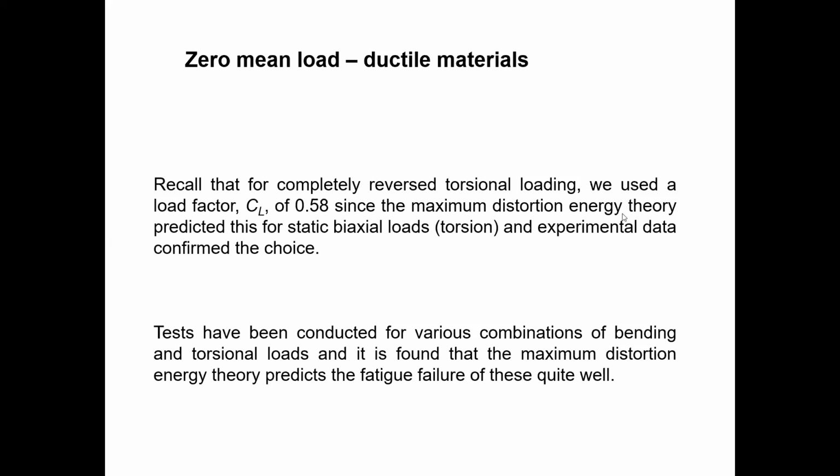Since the maximum distortion energy theory predicts this for static biaxial load and torsion, experimental data confirm the choice. Yes, we already discussed this one because we need this one. That's why I explain here. Tests have been conducted for various combinations of bending and torsion load, and it is found that the maximum distortion energy theory predicts the fatigue failure of these quite well.